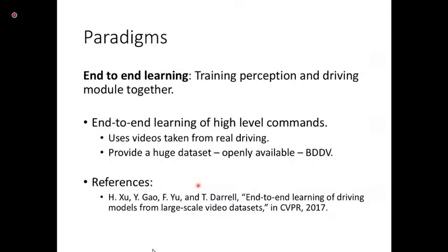So what is affordance learning? Affordance learning says that you don't directly learn the controller action. Instead, you learn some high level commands from the image.